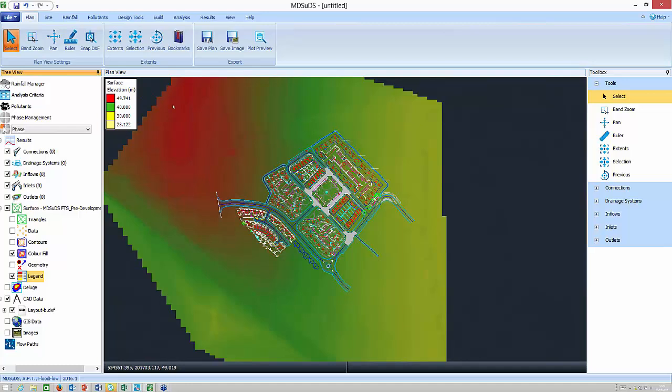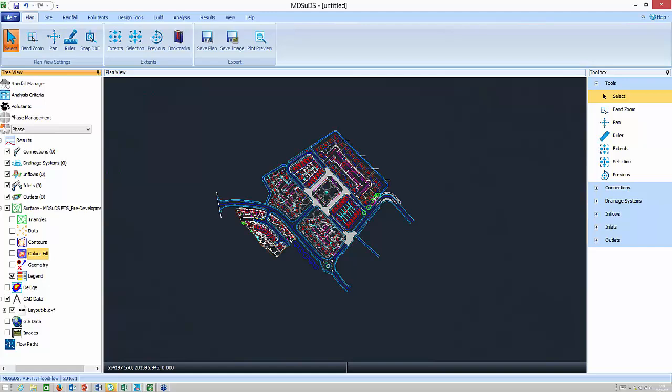So basically, the water looks as though it's going to travel from the west, kind of southeast, I would say, across towards this side. So the outfalls are going to be over to the eastern side of the site, or outfall. It's just kind of helping us scoping out and start to picture what we would like to put in place. We can interrogate the CAD drawing and see what room we have to incorporate different things, and just help with this concept stage.